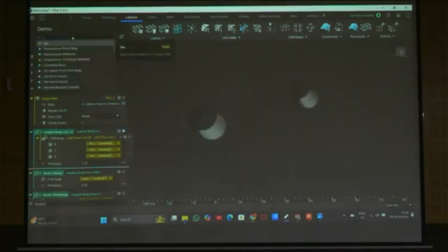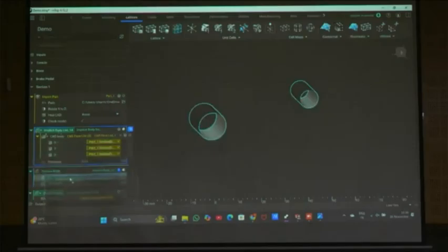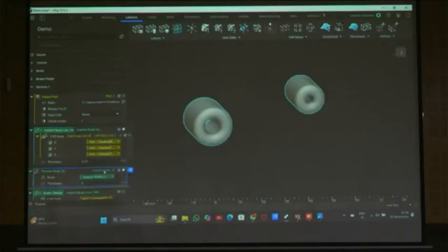So I can apply the thickness to the faces. These are the surfaces, so I will apply the thickness to the surface. Thicken body, so I will drag this. See, the symbol is same. I will drag this. I can apply the thickness 5 mm, okay? This is okay?